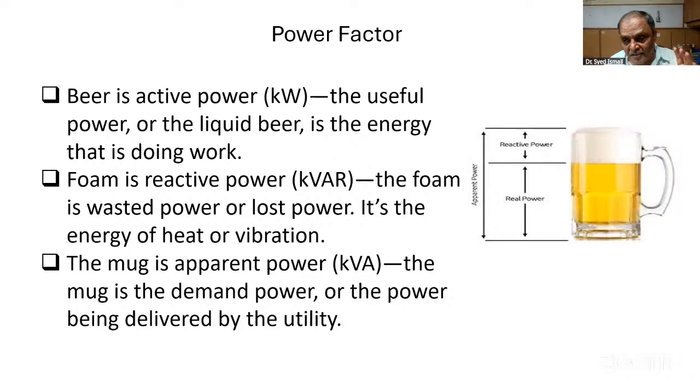So we have to see that every motor has a capacitor bank. That much agriculture people will see to it. We can save 15% of energy in India, in every farm, if you guarantee there is a capacitor bank. It's very cheap. Capacitors are in the motors they are using. That's all we are required to do.